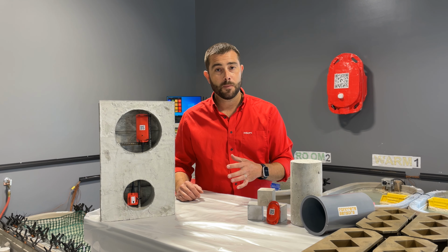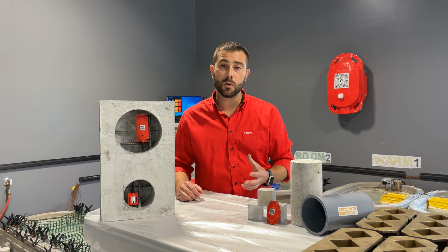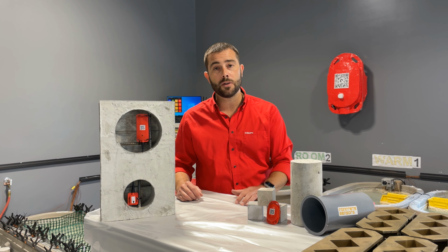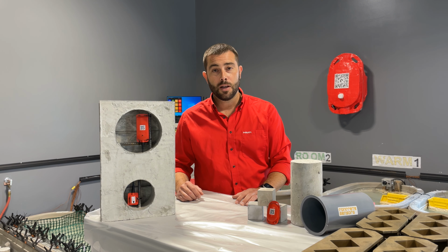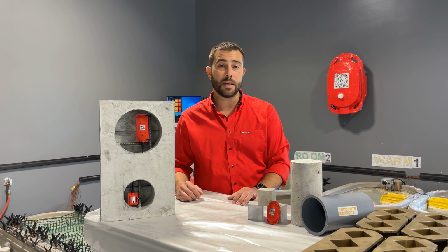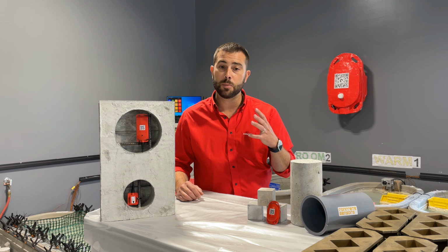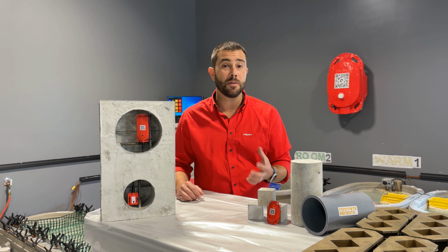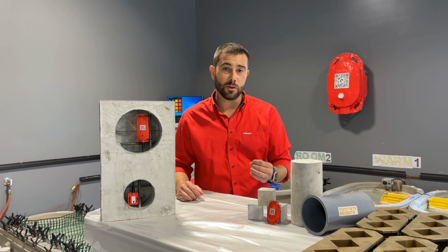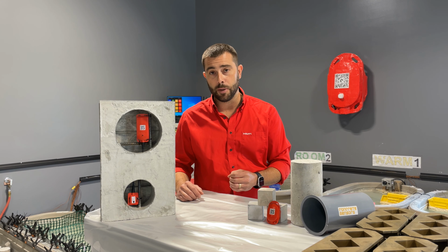The concept was developed in the early 1950s and then later standardized in 1987. You can find it in ASTM C1074. Now the maturity method is a technique that's used to provide a more accurate estimate of the effects of time and temperature of concrete strength development.